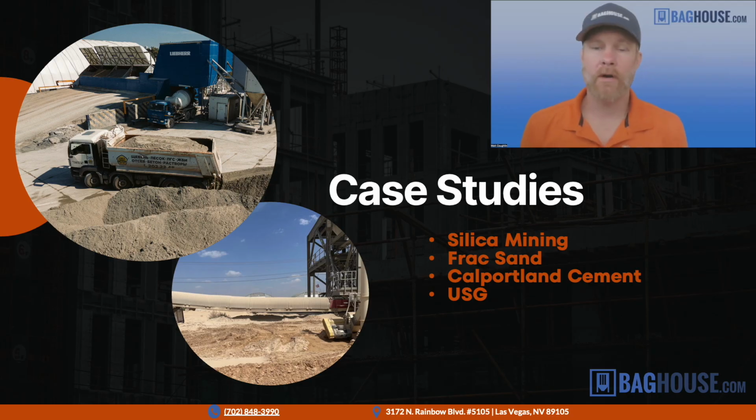A couple of the very common things we saw from site to site was, number one, because silica dust is highly abrasive and a lot of these systems are years or decades old, there's a lot of degradation just due to abrasive dust wearing through ductwork, vent hoods, enclosures, and dust collection equipment.